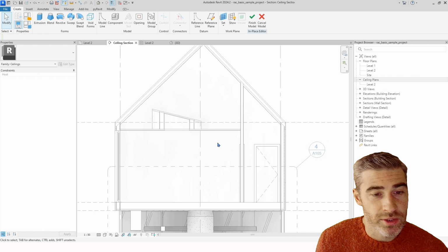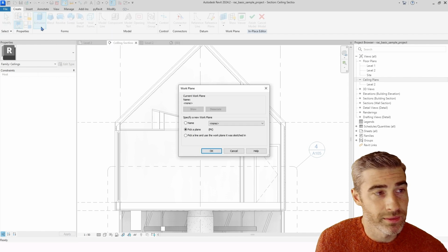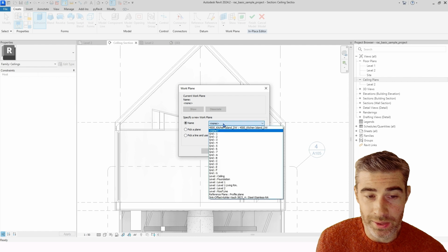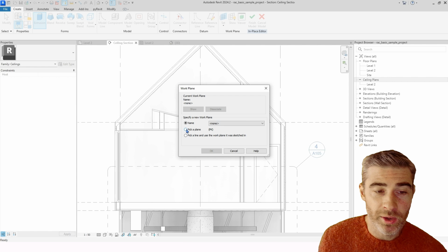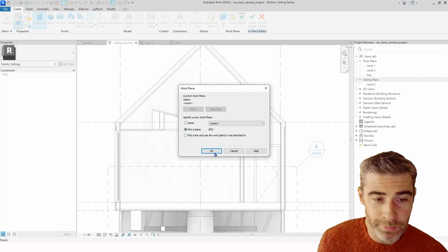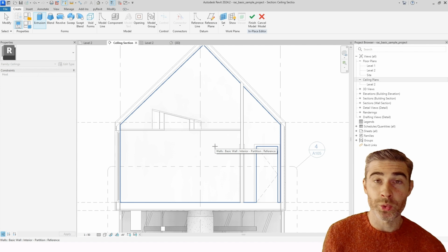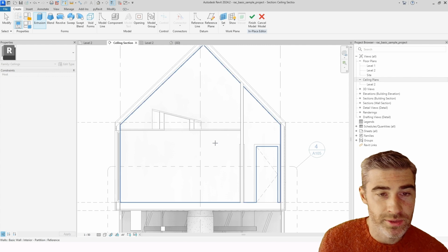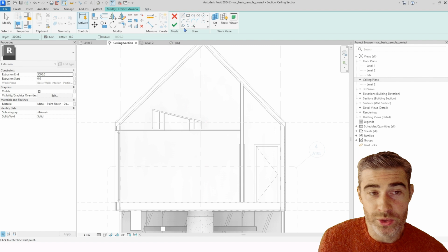So it's going to ask us to start to create this extrusion. It's going to ask us to pick a plane. So you can find a reference name, select the reference that you want to create this from, or you can pick a plane. I'm going to pick a plane for this example, where I want to create this profile so that I can extrude throughout the room. So I'm going to hit this as my plane to work with. And then my draw tools come up.